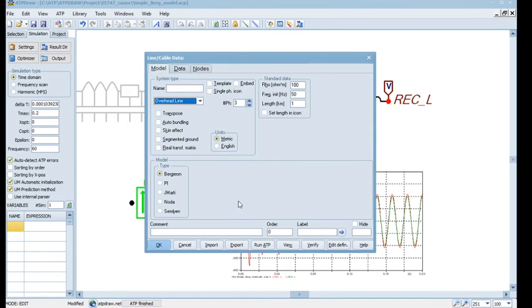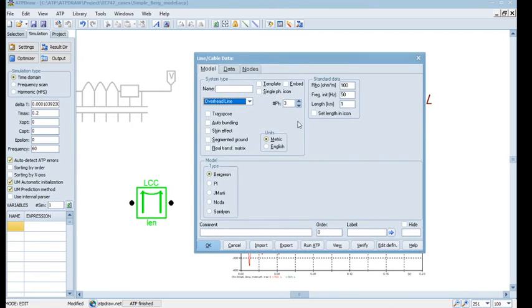The idea is that this is the major tool which is mainly used for 3-phase, but you can always downgrade or upgrade to 6-phase, 10-phase, 20-phase, and so on. Where it happens, for example, if you have a transmission tower with 2 circuits or 4 circuits going together, you need to build that appropriately. A single transmission tower has only one circuit, which is a combination of an R phase, Y phase, and B phase, or ABC phases. But on the other side, you will have another ABC. That becomes a double circuit, so you need to assign this as 6-phase, and so on.